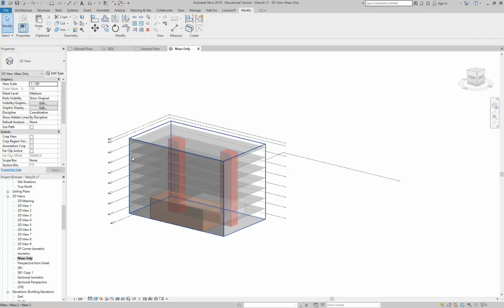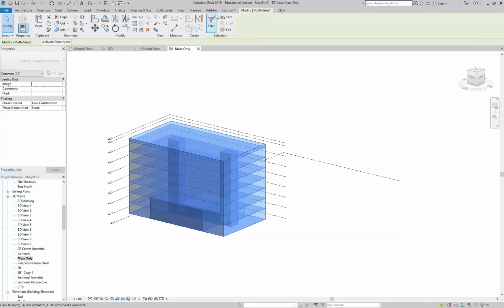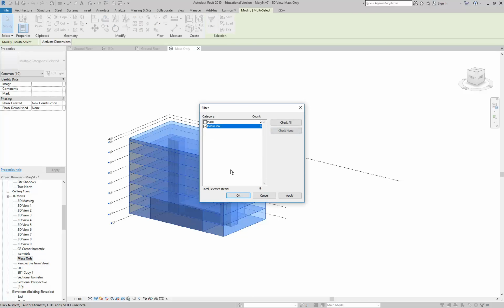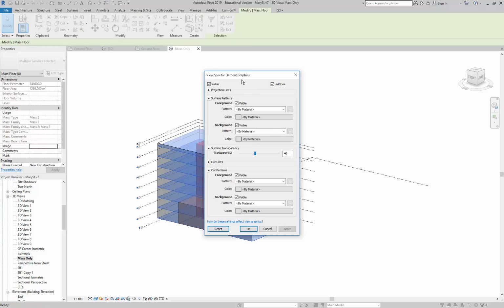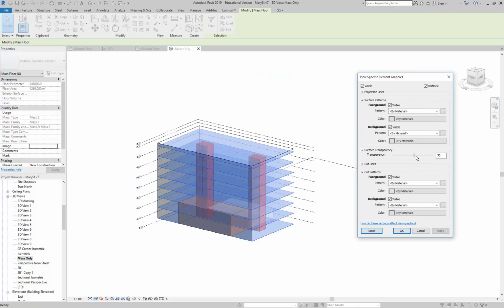Yeah, I should have just applied. You're spot on. So that's right, and you can stay in the dialog box. So that's the point of apply. And so if I go back into override, by element, and now you keep that up, and then just experiment. So if we move this, and the nice thing is when you hit apply with Revit, this is one thing they got right, it shows you the result of your change without them being selected, which is a really nice feature. So you can test it out, and I want them fairly faint but still visible, and that's probably a nice way of showing things.